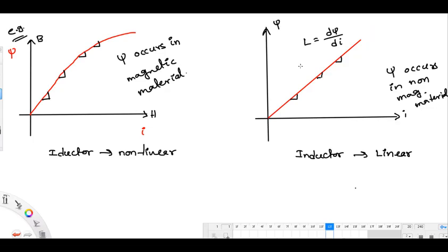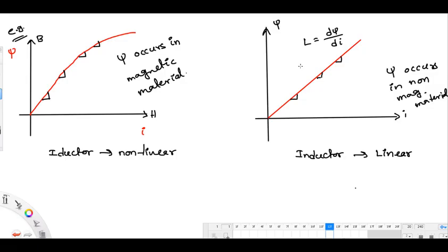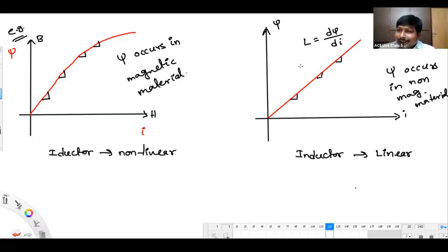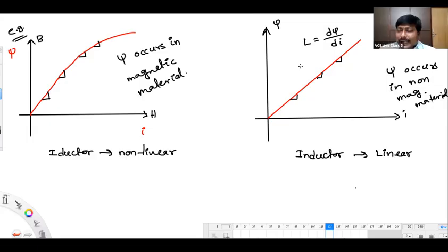And when we try to increase the safety, at that time we need to increase tensile strength. You are going to compare ACSR with solid, is it? No, sir. In AAC only. By increasing mechanical strength, by adding that steel, ACSR will have less advantage in transportation compared to AAC. Yes, sir. That's correct. But compared to solid, ACSR transportation is easy. So in that way, we are getting the advantage of transportation as well as skin effect by going with the ACSR. Understood.